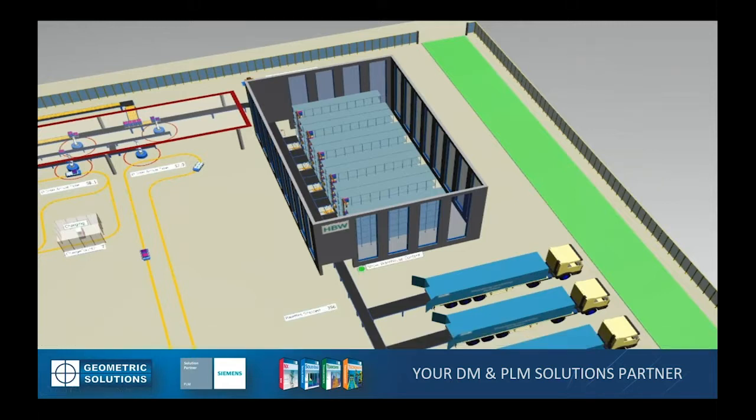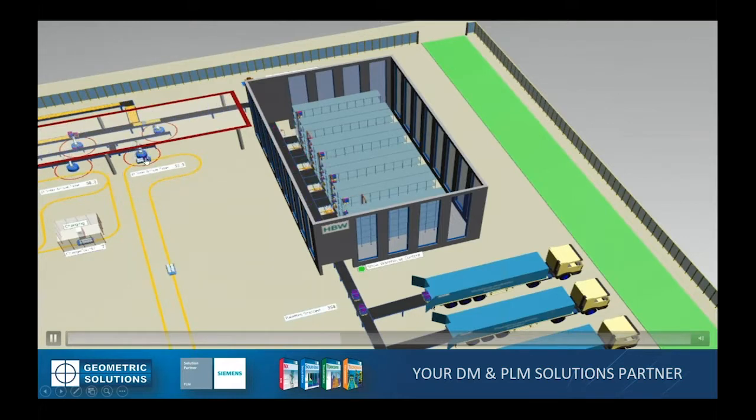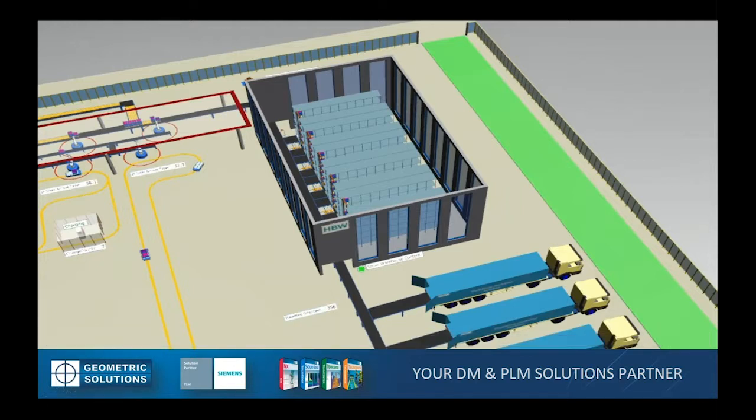For example, this is a pick and place machine over here that stays there until the part's gone. If this doesn't fire, and I might have 4 or 5 AGVs sitting up here, I can test the logic for communicating between these two devices to make sure that parts are moving. So when the parts disappear from the AGV, the part presence sensor then sends a signal to the AGV that you could move forward, and we can test all that stuff out.